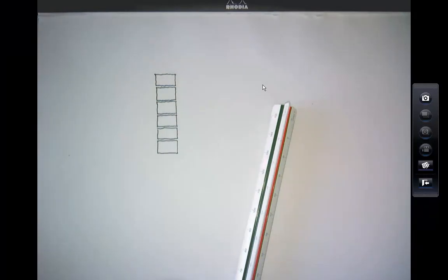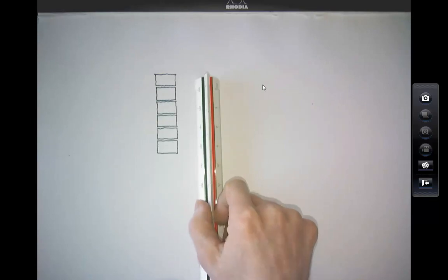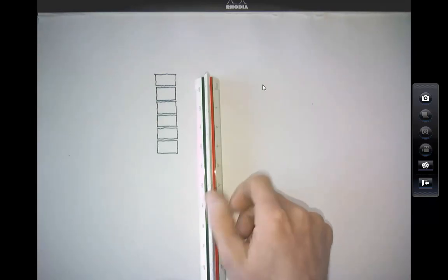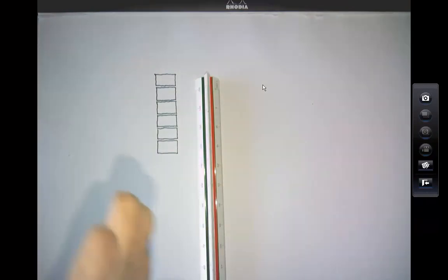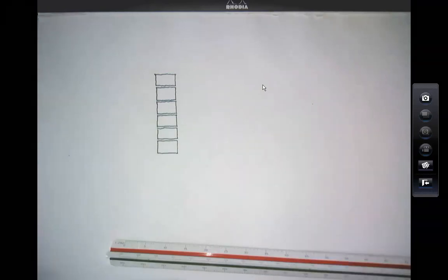Now, the next thing to understand with most modern brickwork is we're not building the inner leaf typically in block. So when you're doing a domestic building, a house, you're probably quite familiar that the inner skin would be a skin of blockwork, concrete blockwork. Now, for most larger buildings, blockwork is often considered too slow to build on site. Okay, it's also quite heavy, but the main problem is it's too slow.